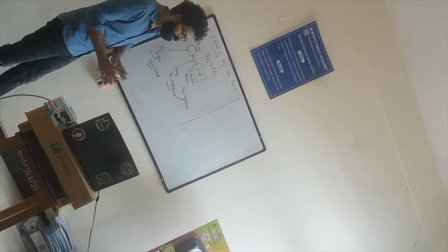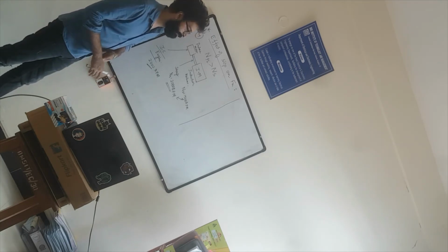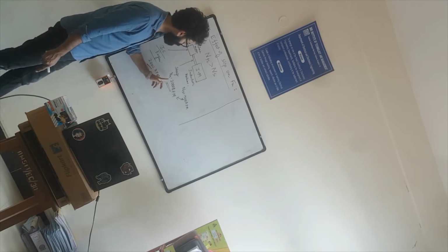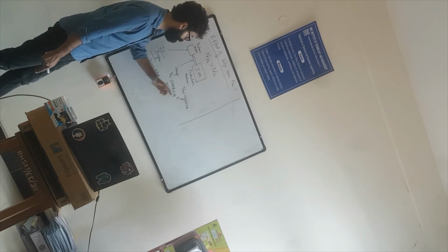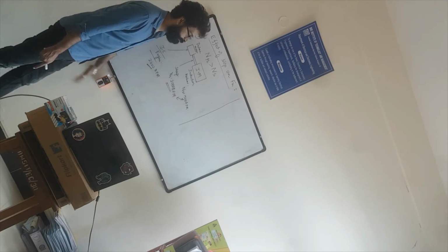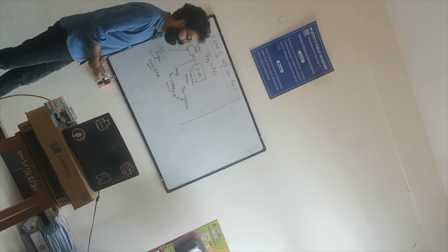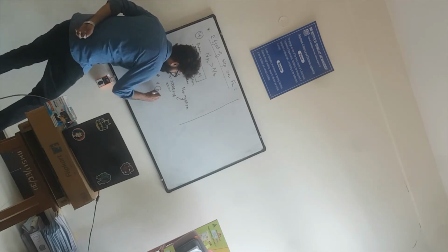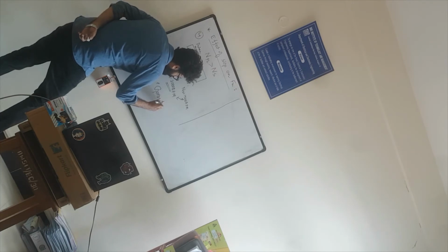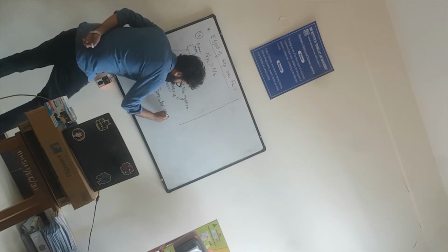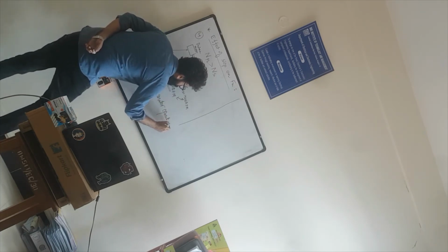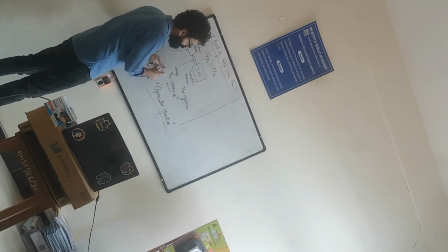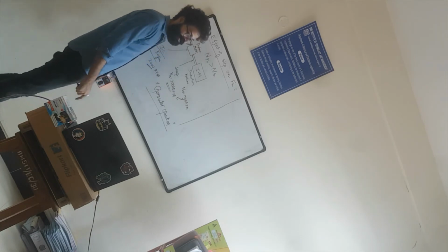RMF is produced when the stator is connected to the electric supply. But in this case, the rotor is rotating at 2000 RPM, which is much greater in comparison with NS. So this particular operation is called generator operation, in which the mechanical energy is overpowering the electrical energy.